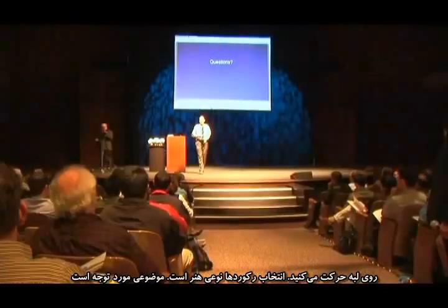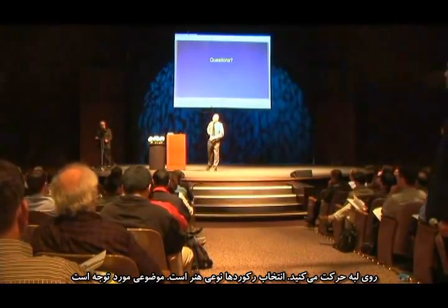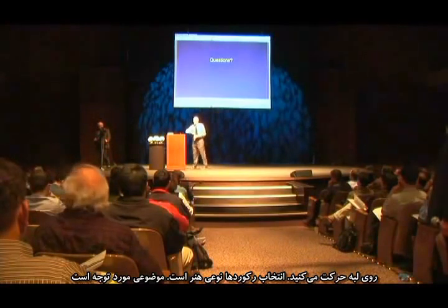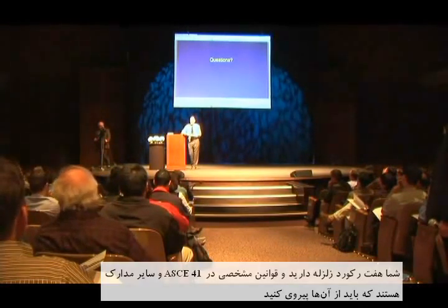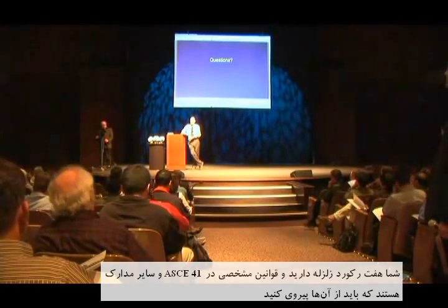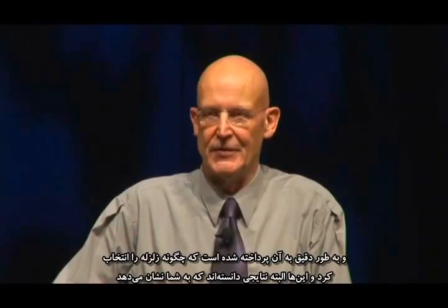Oh, anywhere. You can go online and get them. Choosing the records is a bit of a black art. This is a matter of debate. If you have these 7 records, there are certain rules that ASCE 41 and other documents establish that you should follow. But it is admittedly possible to kind of cherry pick your earthquakes a little bit. There's intense debate in the academic community about exactly how you pick the earthquakes, and this is something of an unresolved issue.